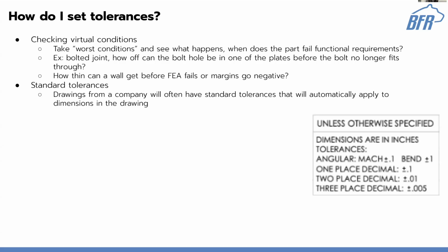And you can do this whole thing of what percentage failure you might have. But that's one thing. Some things are also structural, right? If I have a cutout that's a slot and it ends up being too large, now I have a wall nearby that's thinner, and it's a highly loaded part. And now I'm not sure how much it affects my margins of safety with my FEA.